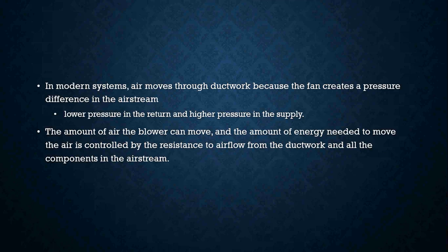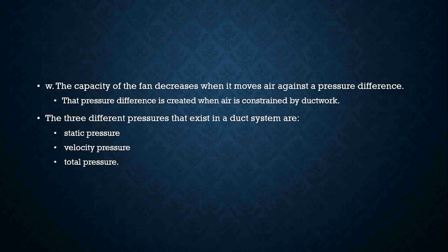For example, if you have an oil-fired furnace with an evaporator coil on top of it, that's a restriction. Now the blower has to move the air not only through a heat exchanger, but it also has to move the air through an evaporator for air conditioning. That takes energy. So CFM is important to make sure that we have the correct amount of airflow through that unit so that we can condition a space efficiently.